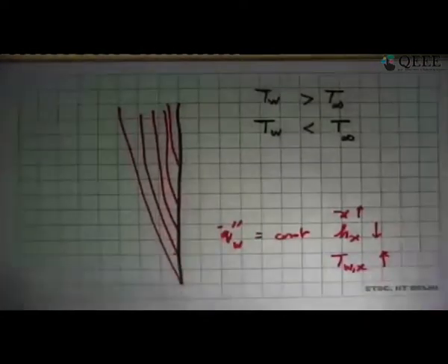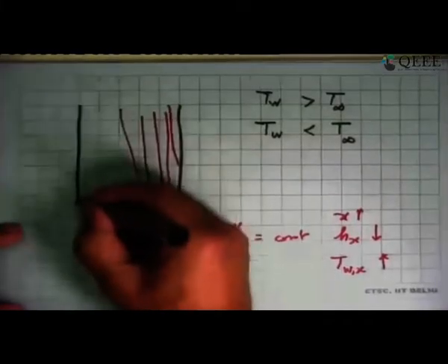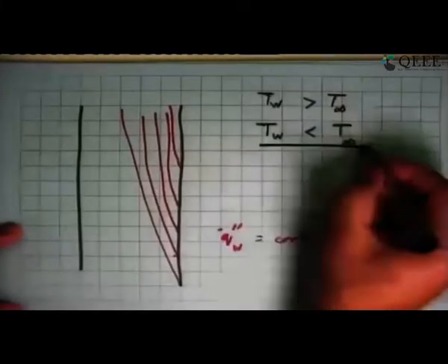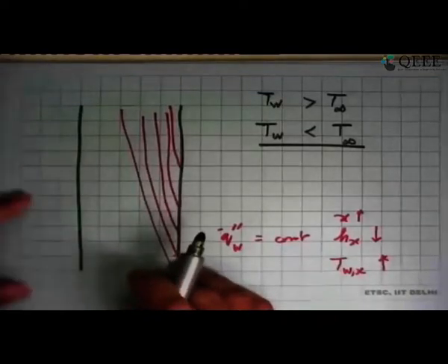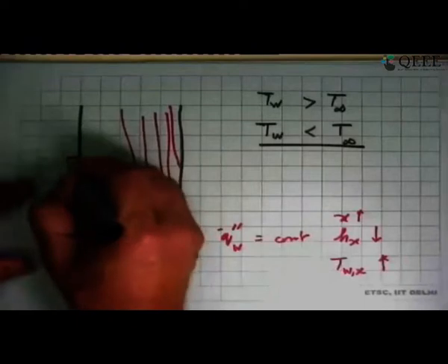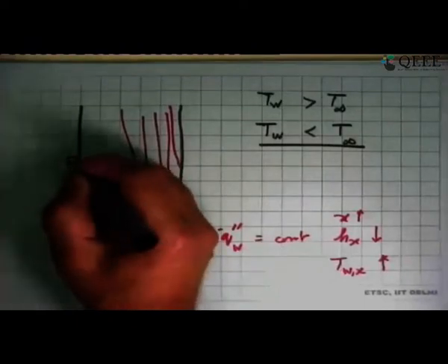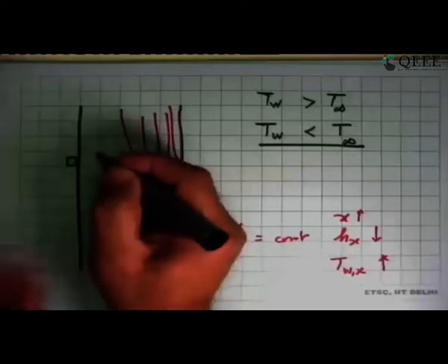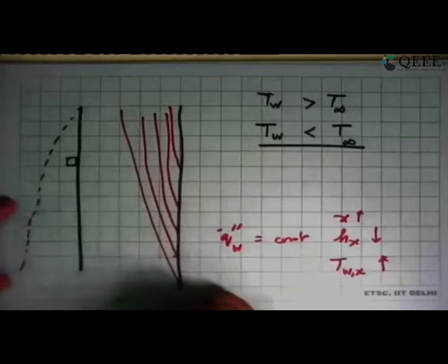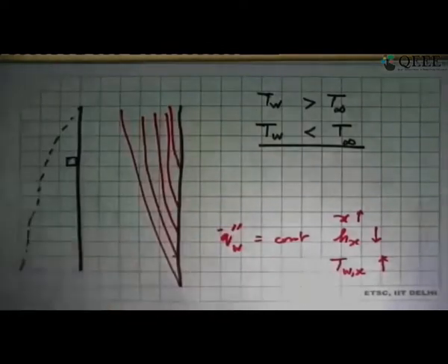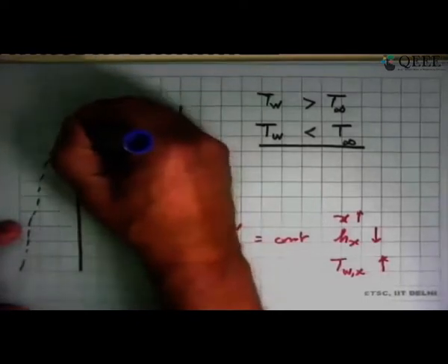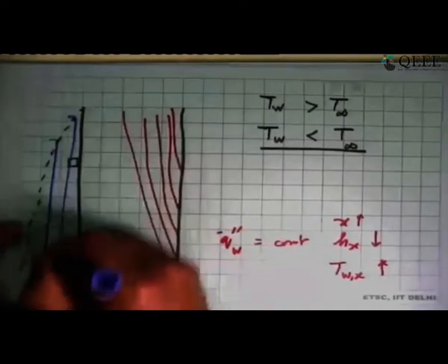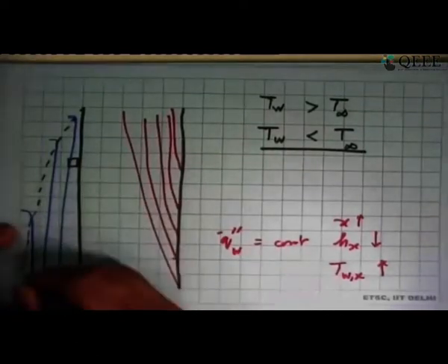And I'll just draw one case that if this is a plate where wall temperature is less than T infinity, then we know that exactly the opposite will happen. A fluid element here which is close to the wall will become colder, its density will increase, it will begin to fall down. And so you'll have a boundary layer building up on this, which happens like that. And all the flow that you would see is happening with a small velocity there, and then this is going down, a small velocity there, and this goes down, small velocity there, it goes down, and you have cold fluid falling down.